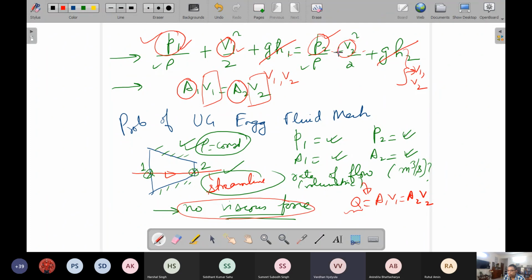If there is a no-slip boundary condition, the profile is like a parabola. But if there is a slip at the wall, maybe at a given cross section, at all the points the velocity is a constant value. Let me put up a different practical example.